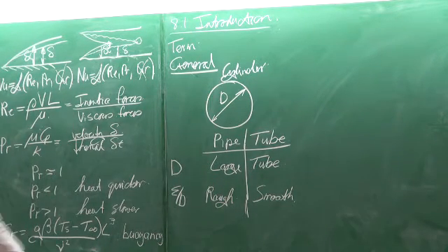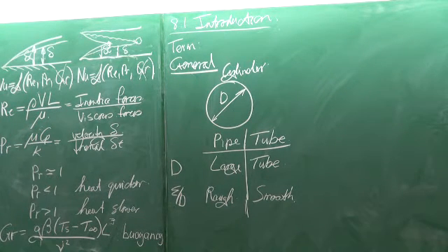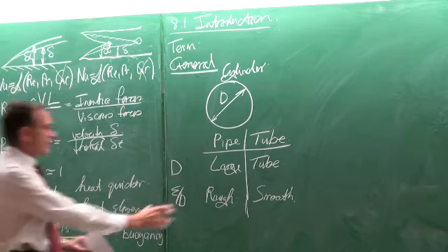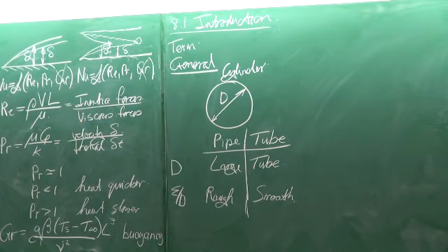So epsilon divided by D is approximately equal to 0. The reason is that all tubes these days are soft-drawn or hard-drawn tubes. The technique is different from 50, 60, 100 years ago when they were cast, and then they were very rough. But these days, that doesn't happen a lot.